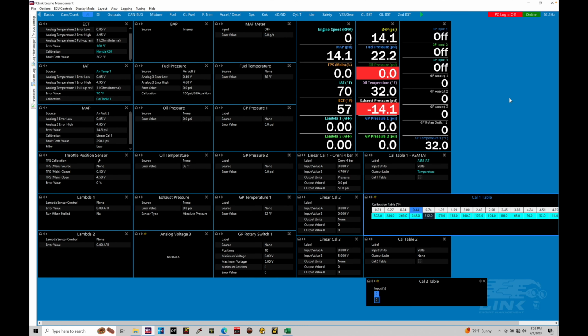Okay, let's jump back in here. That is going to be it for setting up temperature sensors. Again, I'll have to double check this engine coolant temp because it should be matching within maybe 2-3 degrees of our air temp sensor. And in the garage, I was thinking it's about mid-60s. It's probably closer to 70 realistically. So it's going to point to my engine coolant temp sensor not being, in my opinion here, calibrated correctly. So there could be something wrong with this calibration scale. However, that is going to be how we set up our temp sensor inputs.